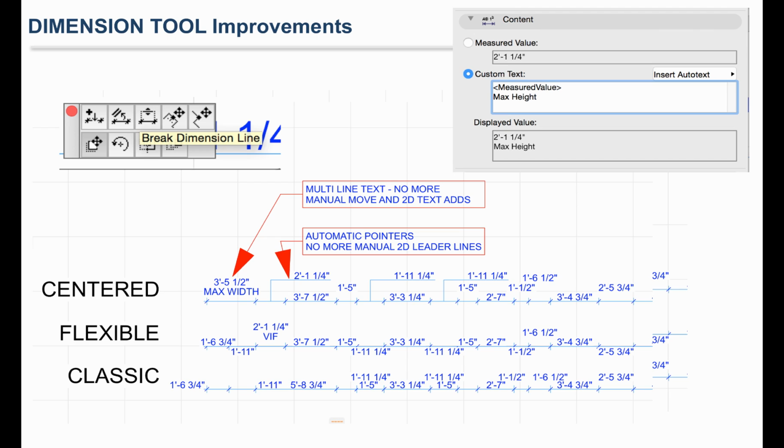Dimensioning narrow structures close to each other can make it difficult to read plans because the dimension numbers are too crowded. Until now, users solve this by dragging the dimension text away and using a manual pointer to connect them to the referred element. The new pointer for the dimension text eliminates this extra work. Add a pointer line to any dimension text. The pointer line is added automatically. When the dimension numbers are moved out of the area, then the pointer lines are associative and follow every change.